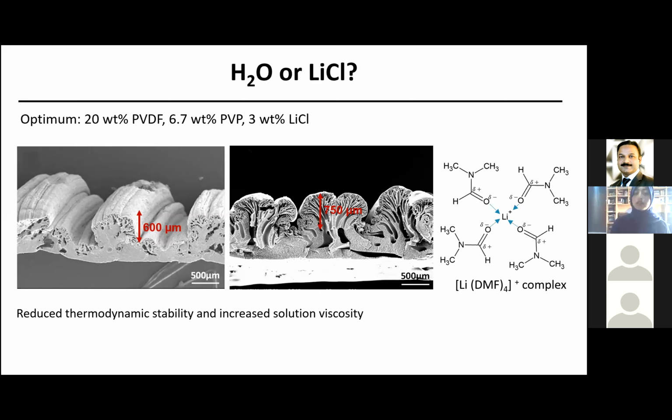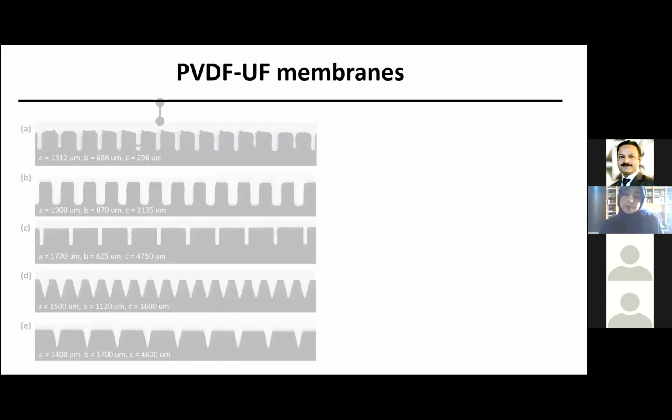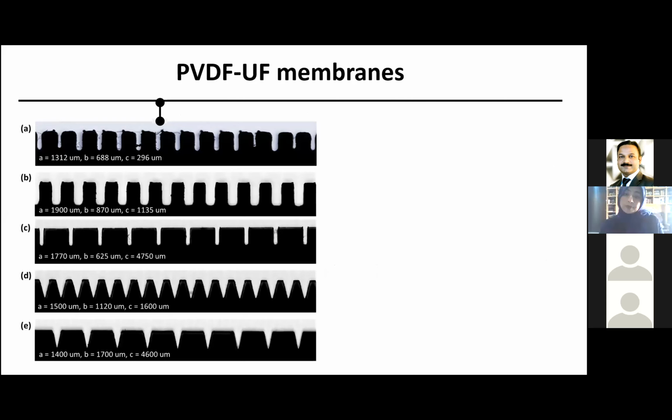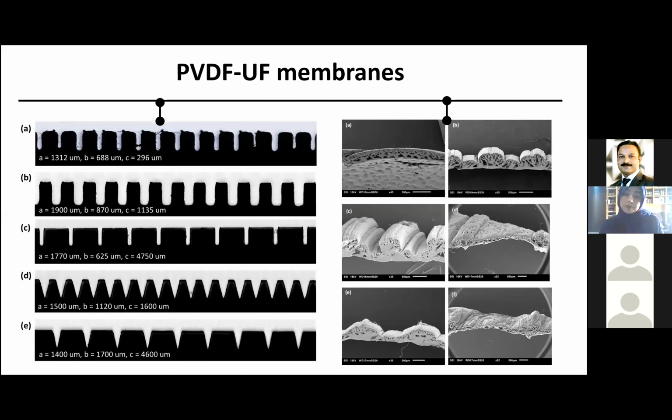So now with this optimum composition, we can have patterned PVDF membranes. We prepared different PVDF ultrafiltration membranes, again using different 3D printed casting knives. Two of them were prepared with very large interpattern distances, which are highlighted here.